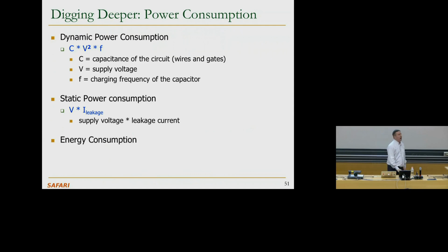So we end up discussing these things. It's not always power. Sometimes we are more interested in energy consumption, especially if you are looking at a battery-operated device. It's actually how much work you do with the power. So it's power times time gives you the energy, and your battery contains a certain amount of joules, a certain amount of energy, and you are concerned about how much can I do with this amount of energy. Because reducing the power, well, you can make it zero, but you are also not doing anything.